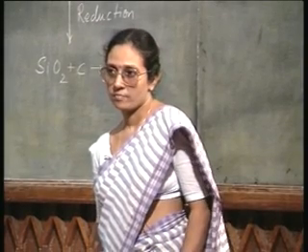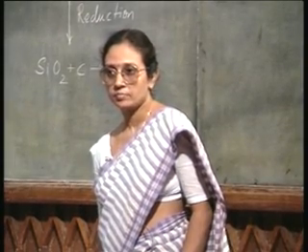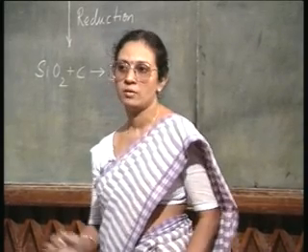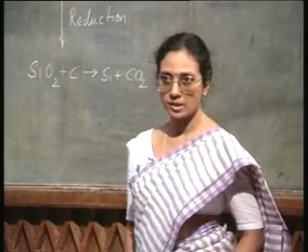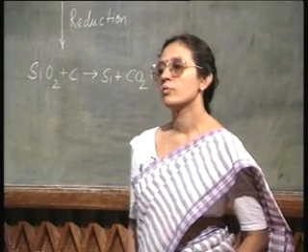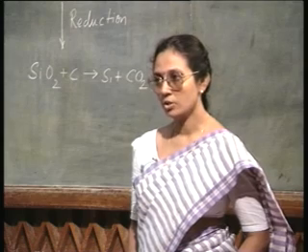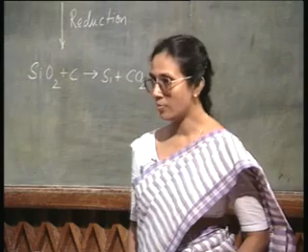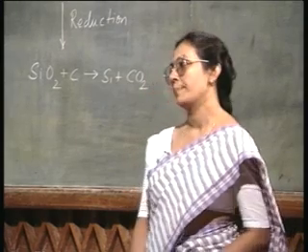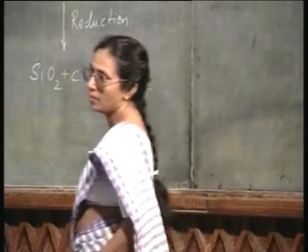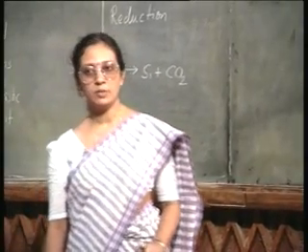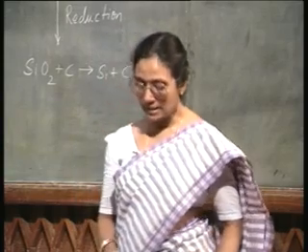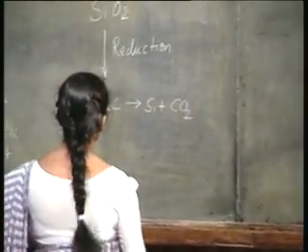You take silicon dioxide, pure silicon dioxide, okay. You have to purify the naturally available silicon dioxide, and then you have to subject it to carbothermic reduction, when you get polycrystalline silicon also of very high purity. Okay. Now that this polycrystalline silicon is available, one has to grow the single crystal, and in this two techniques are used.